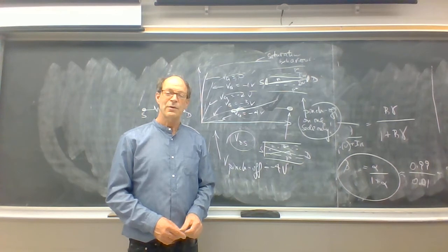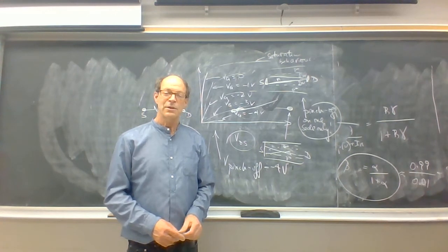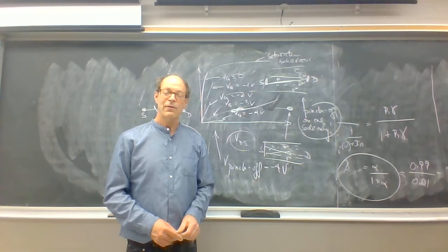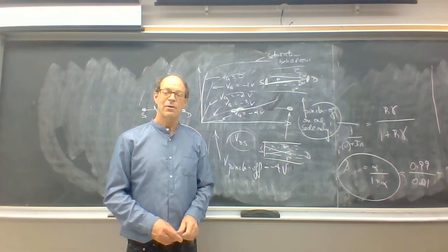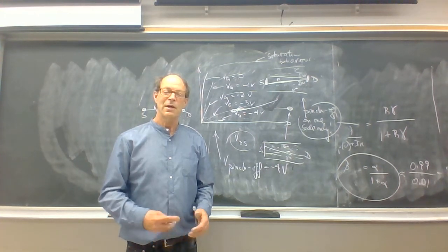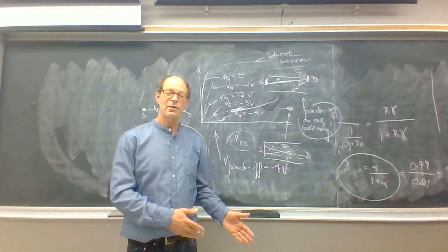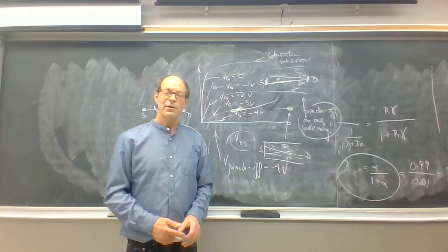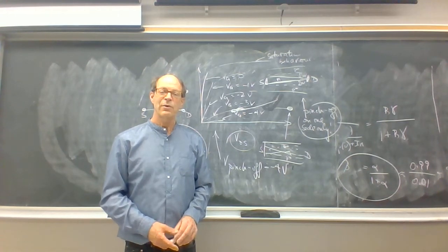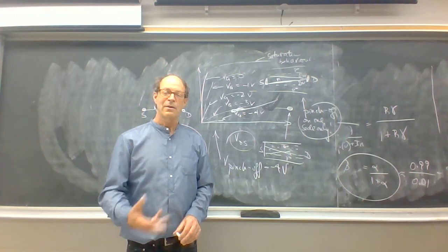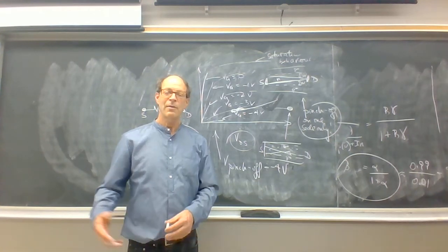The gate is a reverse biased PN junction, and in reverse bias, you know from chapter 3 that the current flow is I0, which is extremely small. So you would expect virtually no current flow into the gate. That means that you can regard the JFET as a virtually infinite input impedance device. And that has benefits if you're trying to detect voltage, to build an operational amplifier, to detect very, very weak signals. Those very weak signals can be detected without demanding current from them when you're trying to amplify them.